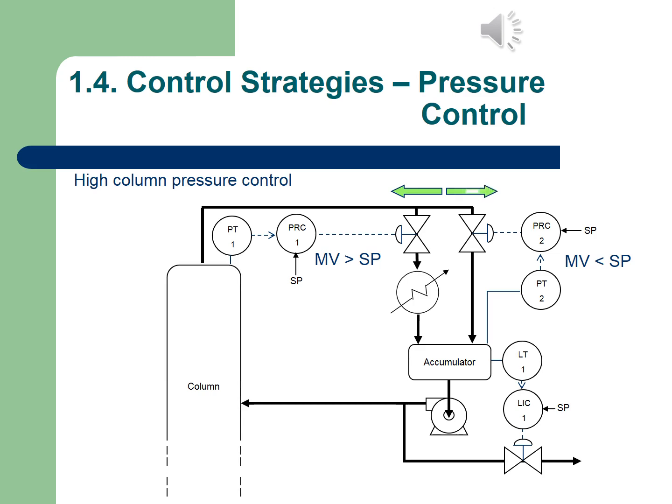So both the two valves can be open in such a case. If the column pressure is really high, we can still bypass the heat exchanger on the second leg, so that we can quickly release some of the vapor inside the accumulator. Then it will just condense.